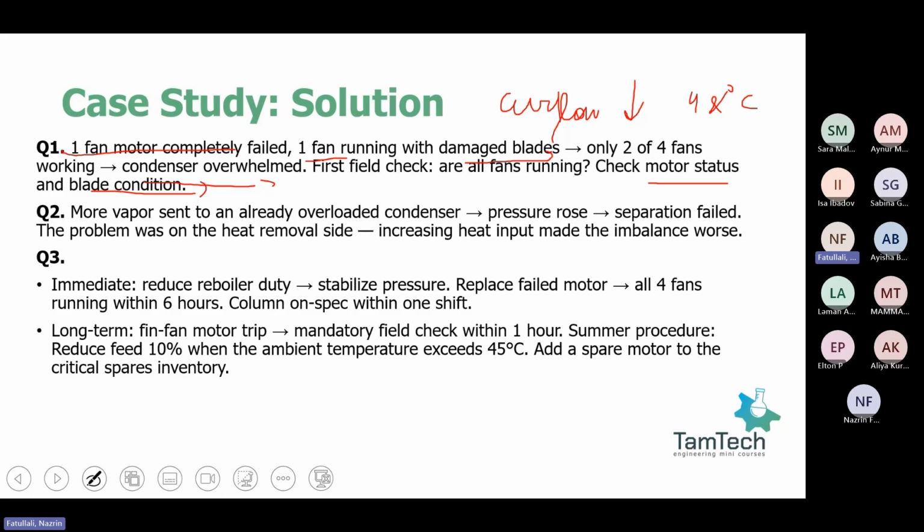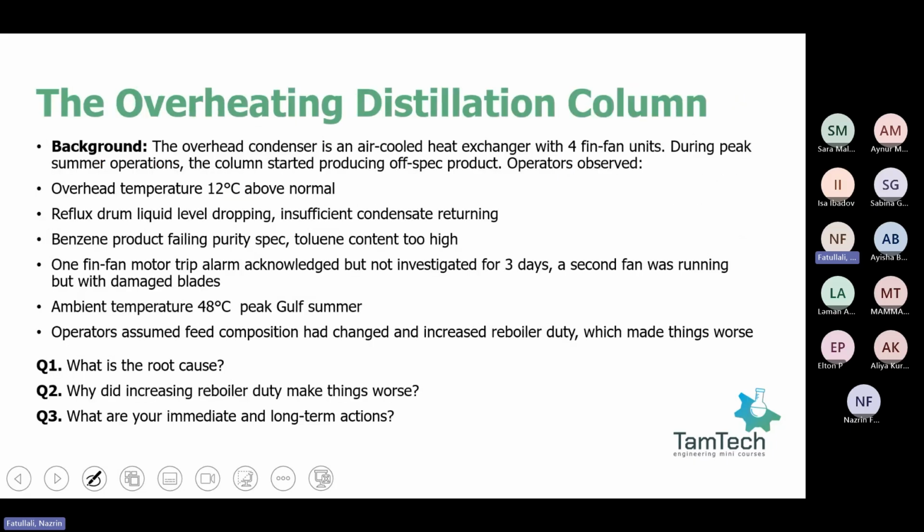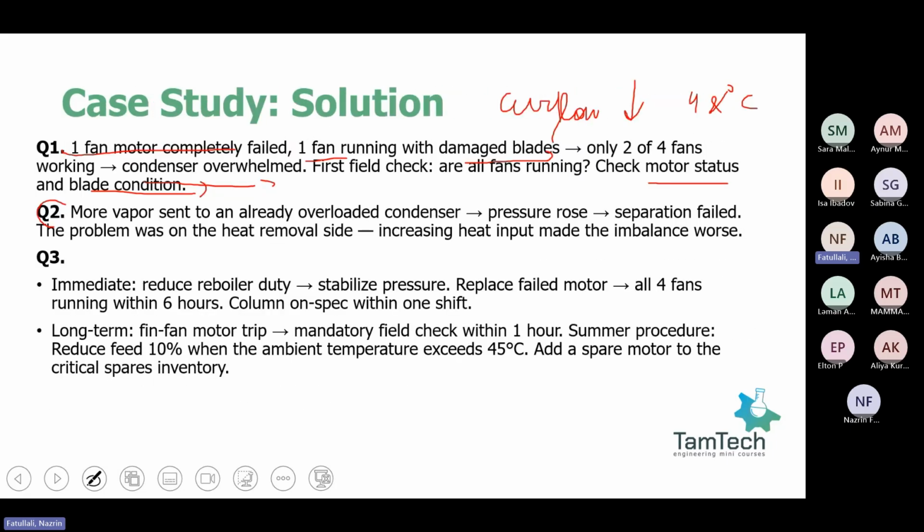Someone clicked on alarm acknowledgement and moved on. There is no solution for this alarm or no logged problem for this. That's the first root cause why this issue happened. It's simple. And the second question is, why did increasing reboiler duty make things worse? First of all, the reboiler, as you know, generates vapor. That vapor has to be condensed at the top.